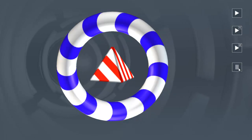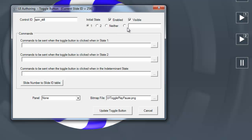So if we hold control down and click on it, it brings up the UI authoring for the toggle button, and at the top here you've got two radio buttons for its initial state. So the initial state, or the first time we see the button, currently is its one state, and what we want it to be is the second state, so that the first time we see the button it has a play symbol on it and not the pause.